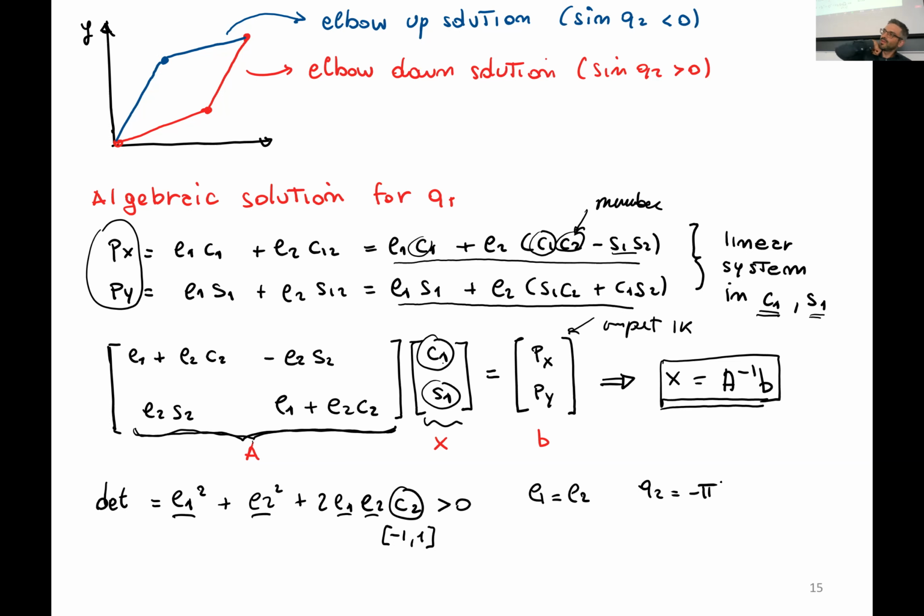You remember that example where we were looking at the Dexter's workspace, where you could have the origin as a part of the workspace, and you have infinite solutions of Q1 that correspond to the end effector. So in this particular situation where you're requiring the end effector to be in the origin, with link length one equal to the other, you have a singular solution and you cannot solve this. So you cannot find your infinite solutions for Q1, which makes sense in this situation.